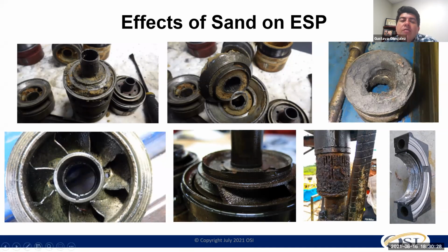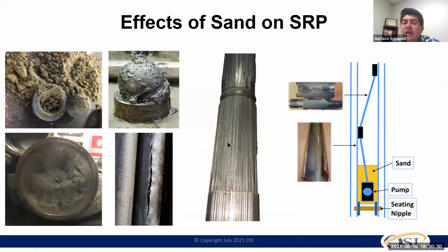On rod pump, what normally happens is the same phenomenon. I get a workover. The amount of sand that is passing through my standing valve, maybe it was okay and I'm able to lift that up without sticking my standing valve. But now that sand has to pass between my plunger and my barrel.